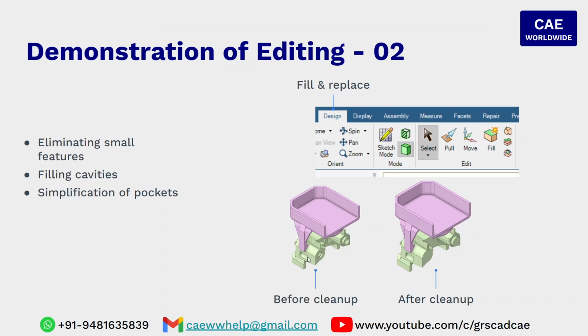In that regard, we may not necessarily need most of these pocket features or the complex features. Those features can be closed. Geometry can be simplified so that the node count can be reduced. How do we handle that particular geometry? We are going to study that now.